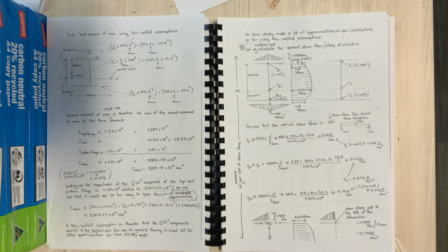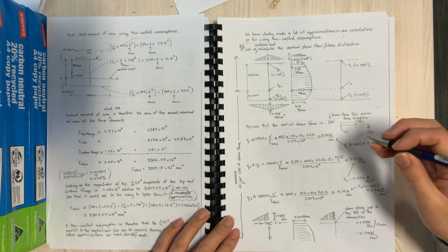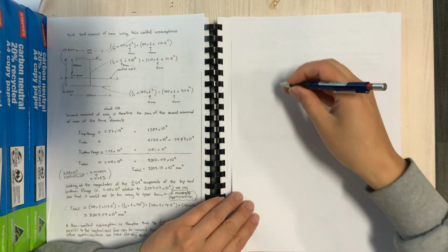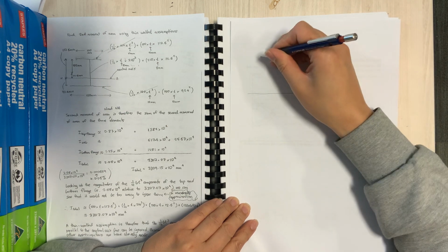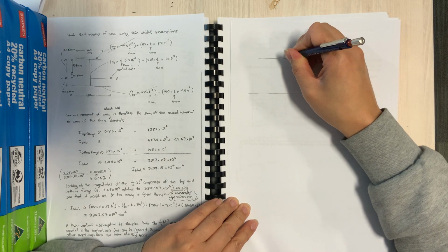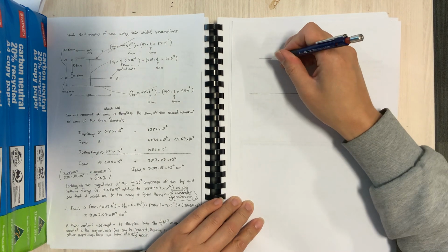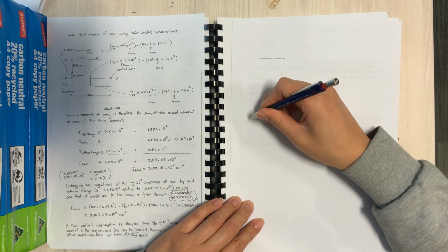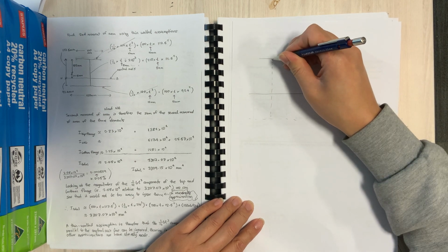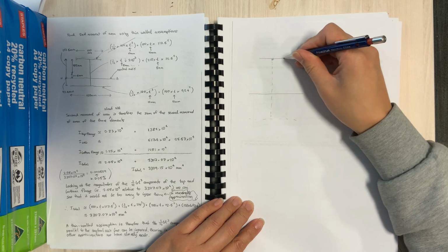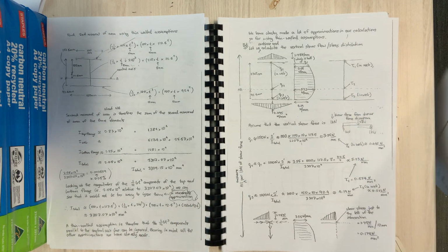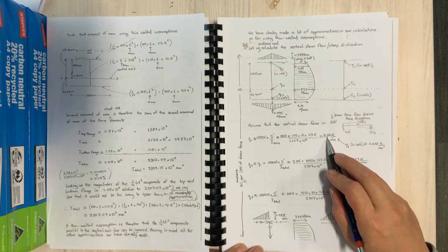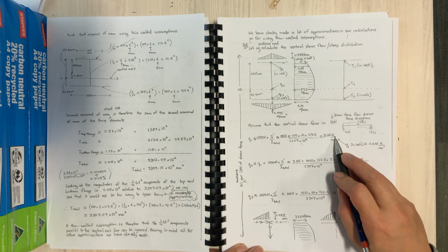So I'll just explain how that one was done. We basically have just said that we've got the neutral axis. Here is the flange up there. We've pretended that we've removed the flange from the section, which will give you the shear flow at that junction. So we work out the area, work out the S dash, and divide by I total, and we get 356 newtons per millimeter.